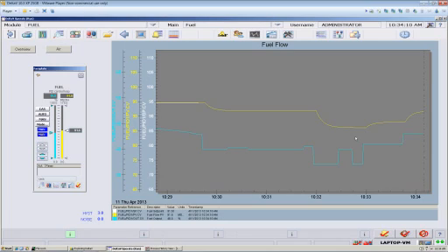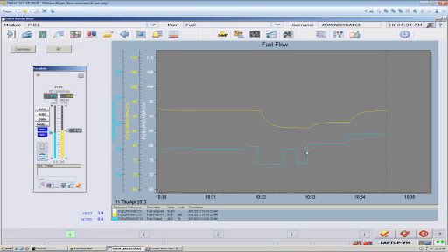So let me talk about just one more type of valve problem. We've been talking about hysteresis or sloppiness here. Another problem that's even more severe and more problematic to our tuning is stickiness. If there's so much friction that the actuator can't overcome it and can't move the valve body, we tell it to open a little bit more and nothing happens, and open a little bit more and nothing happens, and open a little bit more. Now the actuator's developed so much air pressure that it does break free and makes a big jump all at once.